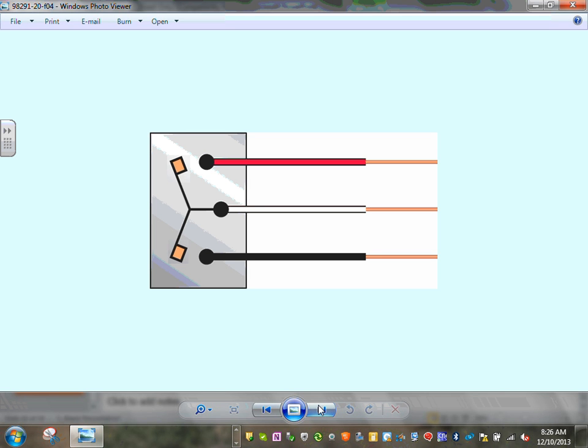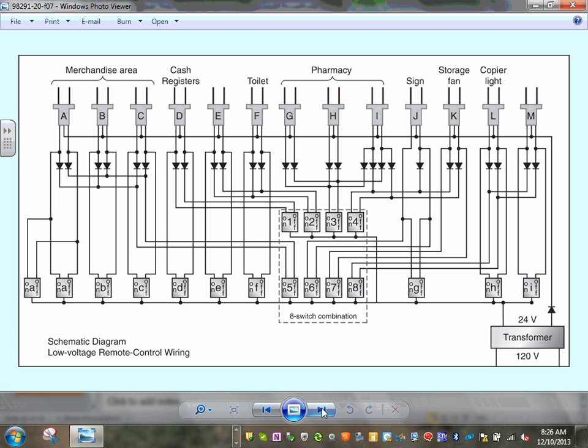This voltage is 24 volt, remember. It doesn't follow the regulation, 24 volt. But you see that white conductor or that blue conductor, guys? You can have one common for say 10, 20 relays. You don't have to have each one have a common. You have multiple commons. So that's how they wire these babies.